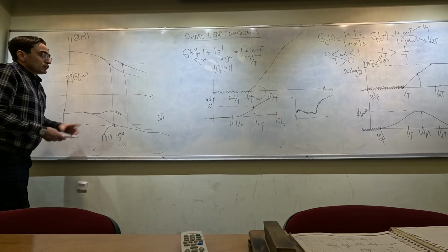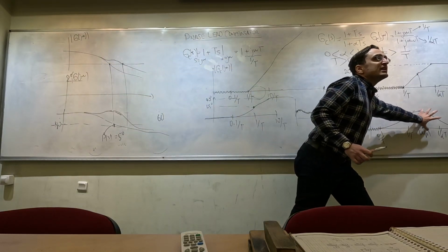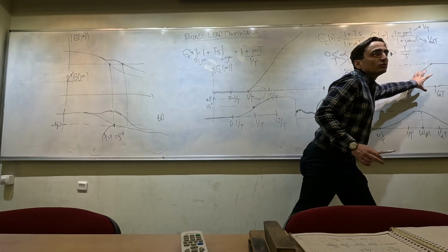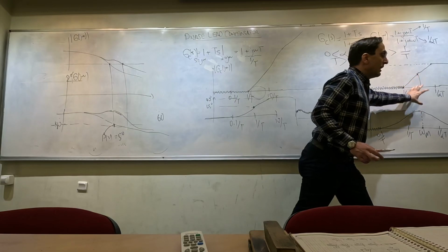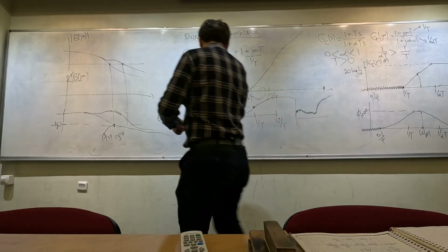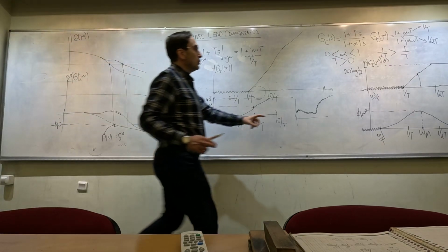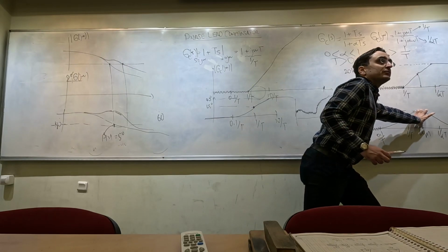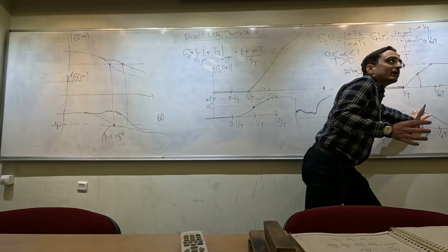So in the phase lead compensator, we are going to benefit from this phase increase, but magnitude is going to be a side effect for us that we are going to try to overcome. For example, if I want to add 55 degree phase, then I'm going to choose these parameters alpha and t such that this peak here is approximately 60 degrees.